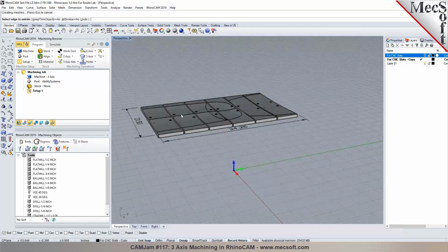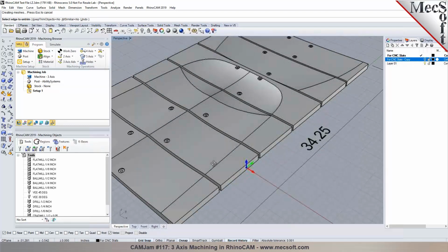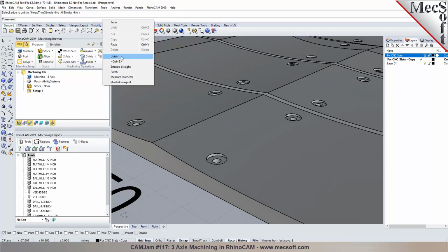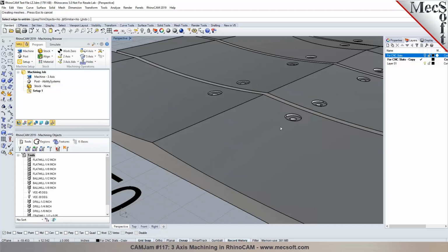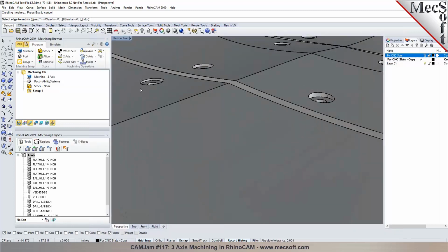Yep. Right. So I may have untrimmed the layer in here, not the other one. You can see that. Yeah. I may have accidentally selected the wrong one. So let me go back and undo all of these here. I'll hide one of the layers before I do it. Okay, so now let me keep one of the copied layers active here, and we'll run the untrim command real quick in Rhino, and you can see that only one of the layers is active. So I'm not picking the holes from the other layer, the one that I copied.